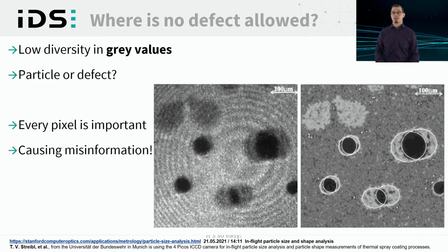Applications which contain such a characteristic are mostly transmitted light methods, like glass inspection. For glass inspection, the algorithm only detects if a defect is present or not. Often it is not possible for the system to recognize where this error comes from. Is this defect caused by the sample or by the camera? In the picture, it is clearly visible, but a particle of dirt in the camera cannot be distinguished from a spot in the sample. With this misinformation, the system produces mistakenly rejected goods.